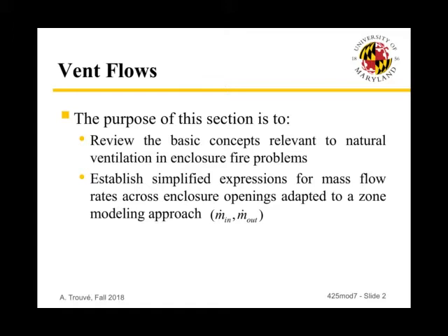From a zone modeling perspective, our goal here is to establish expressions for the mass flow rate m dot in and m dot out. As you may remember, in our governing equations, we have different flow streams. We have the fuel mass loss rate m dot f that is required.